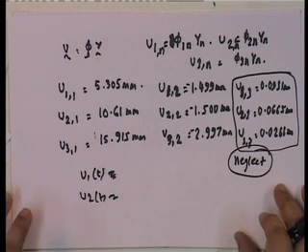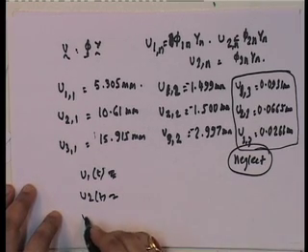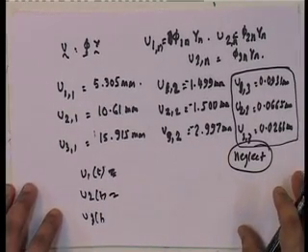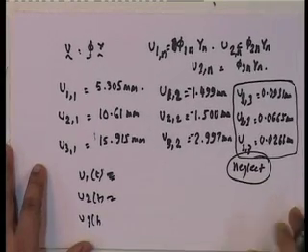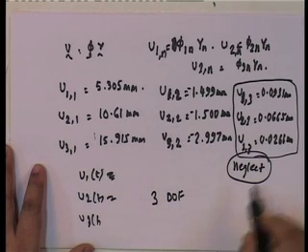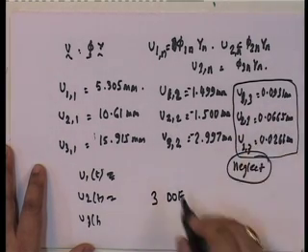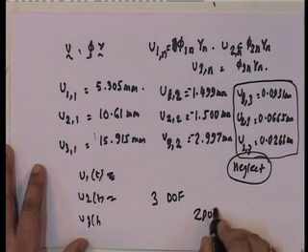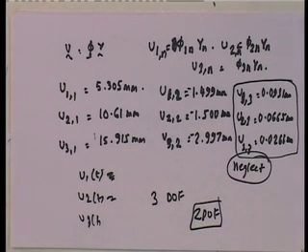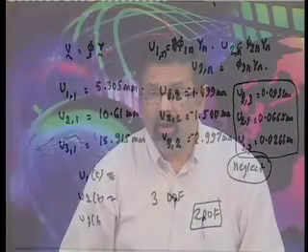Okay. Now, in this particular case, please note, and similarly we can find out V3 of t, which is this plus this sin omega bar t. Now, the question here becomes, look, since I have only 3 degrees of freedom, okay, I do not need to consider the third degree of freedom. So, actually I can just solve the 2 degrees of freedom and be done with it. Okay. Now, this is a very peculiar situation where it is a harmonic load, and the largest displacement is really in the second mode.